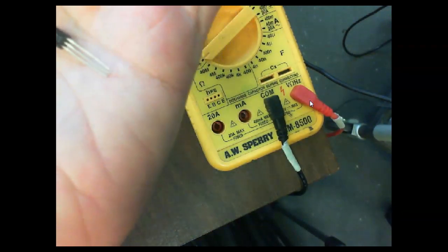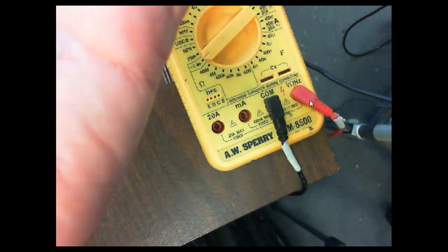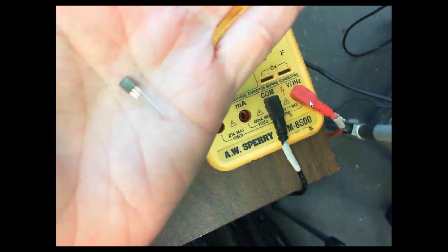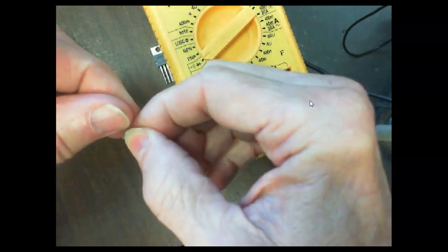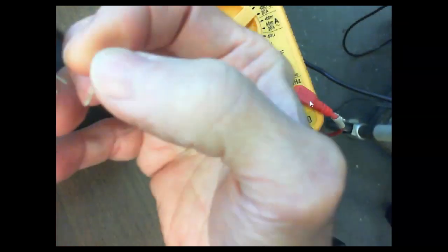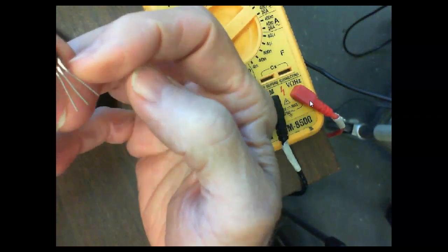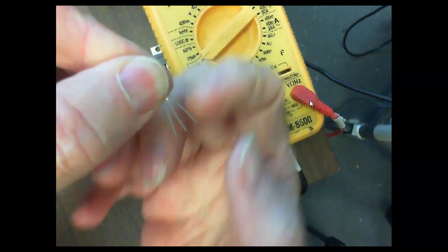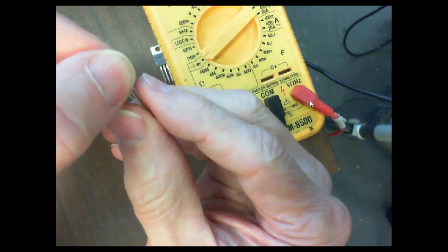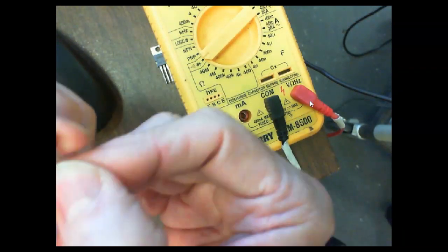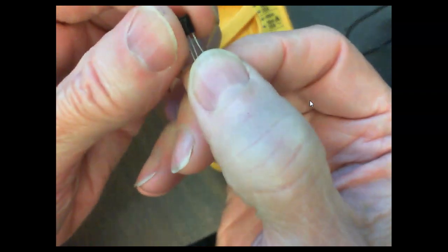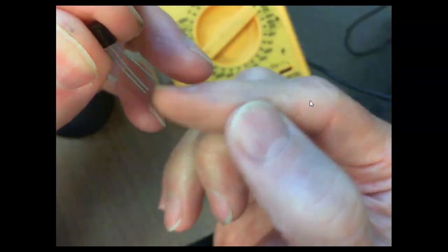So when I come in here and put this in a breadboard, I don't have a breadboard up here. I'm going to put these things in consecutive holes. What happens is students will come up here and they'll bend these leads, and then they'll break off right up here where they go into the transistor. So when you put this thing into the trainer, you're going to put it into consecutive vertical lines, right?